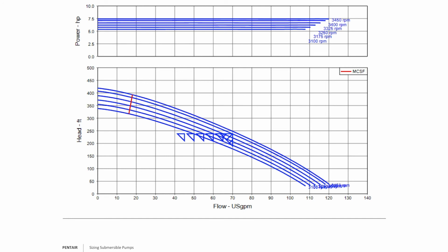Remember, when you pull up a multi-speed curve, just how I told you to correct that one red line, I can go to each line and adjust the RPMs to get them to line up basically with each point of usage, to give the customer an idea of approximately how much RPM it would be. And more importantly, if you look at the power curve, the power HP curve, you'll notice that it gives you less power, of course, with less RPMs. So the customer can look at potential savings that way.